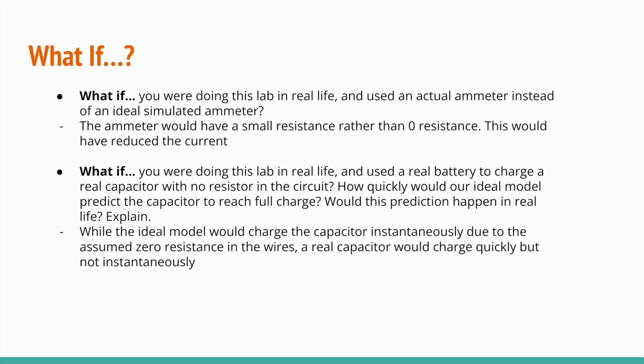Some discussion questions were: if I was doing this lab in real life and used an actual ammeter instead of the ideal simulated ammeter, I would find that the ammeter would have a small resistance rather than zero resistance, which would result in a reduced current value, because higher resistance equals lower current.